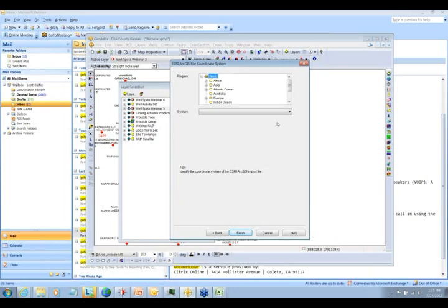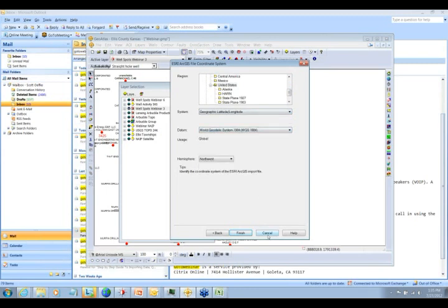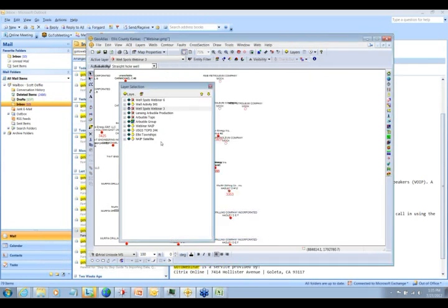Now, some of the services, the subscription services like MapMart and Spatial Energy, actually provide the data in NAD27. And since so many projects are set up with the NAD27 data, that makes it very convenient. You don't have to do the transformation, or the system doesn't have to do the transformation. But go right here, select geographic lat long, WGS84.